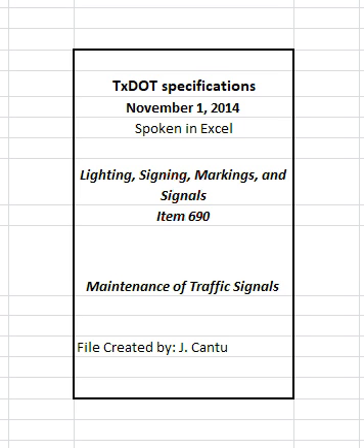4.13 Traffic signal controller cabinet, pole mount. Install, repair, replace, remove, or modify pole-mounted cabinet. Plumb and tighten the cabinet. Coil all cabling that enters the cabinet neatly on the cabinet floor. Mark and terminate each cable as shown on the plans, or as directed.